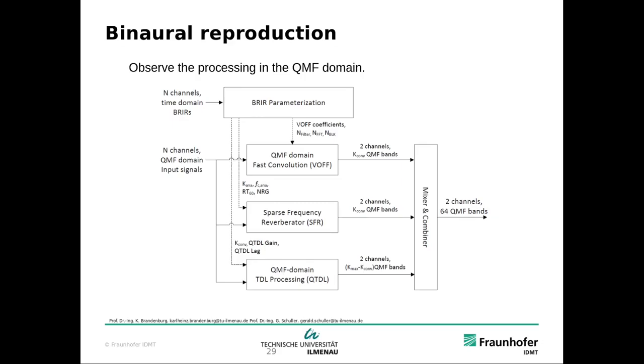So the goal here is not to reconstruct the original signal, but to have maybe one source attenuated and the other one amplified. And that means neighboring subbands can have very different factors. And in the case of the MDCT, this would lead to aliasing artifacts because of the limited attenuation in nearby subbands.